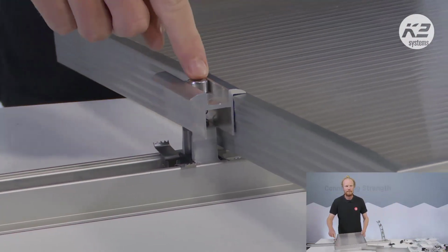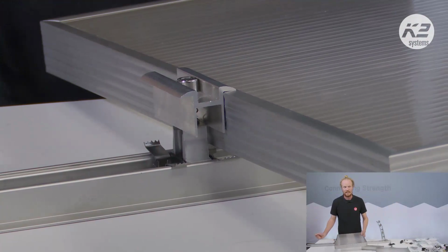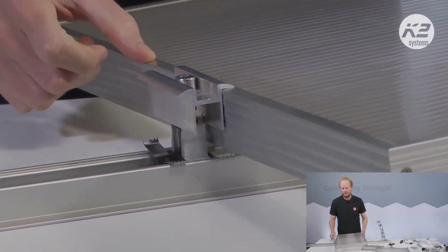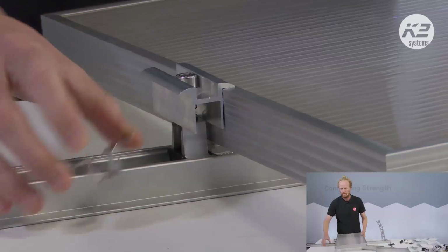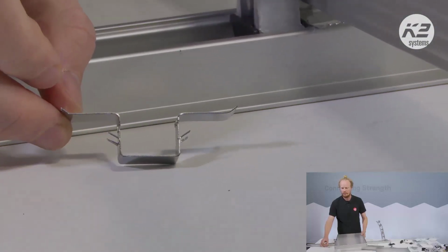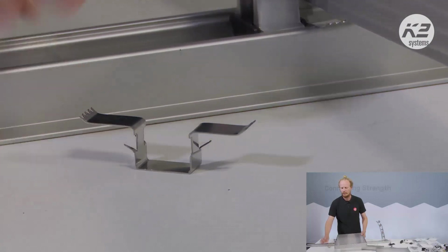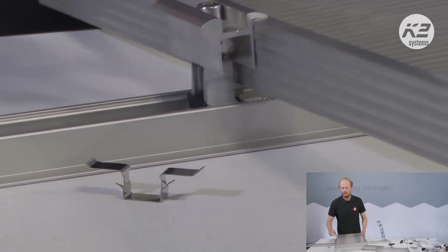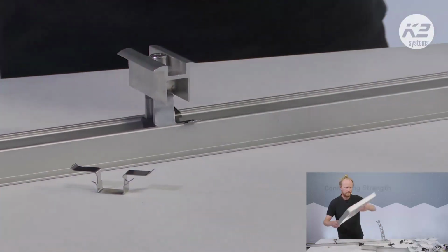And as I tighten from here, these little teeth are going to be pushed out and scratched into the module frame. Then I have little teeth on the inside of the pitch groove, which sits inside the channel, and these will scratch into the rail, so our rail and our module can now be deemed at the same potential.